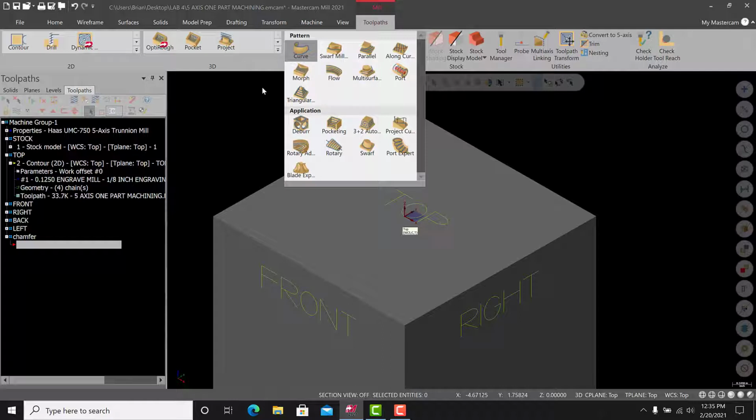And again, this will be the first time we get into simultaneous 5-axis machining, although this is very simple. But more importantly, the UMC has, to my knowledge, it comes stock on those machines. But on other 5-axis machines that Haas carries, I'm not sure about other makers, I know they also have a similar option, but they call it tool center point control. And tool center point control is the simultaneous movement equivalent of dynamic work offsets. So you have DWO and you have TCPC.